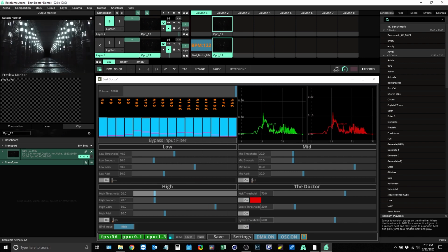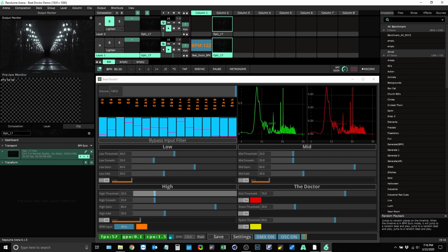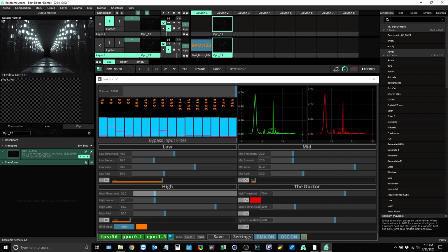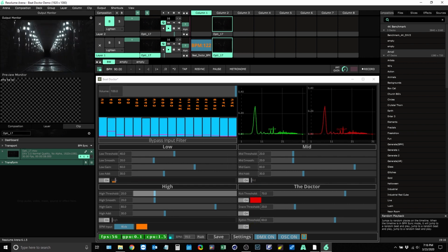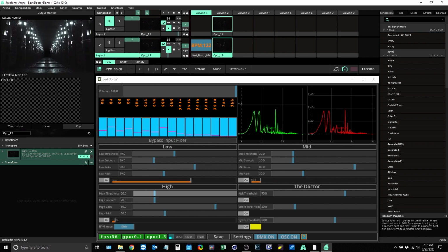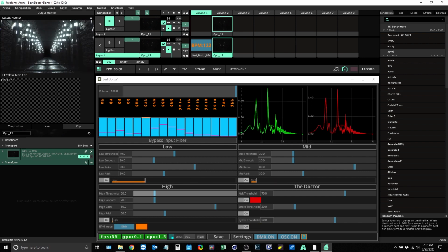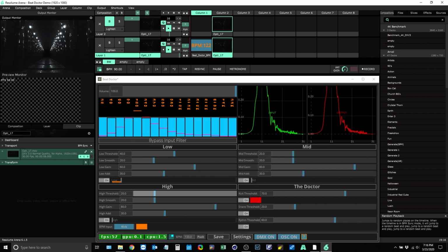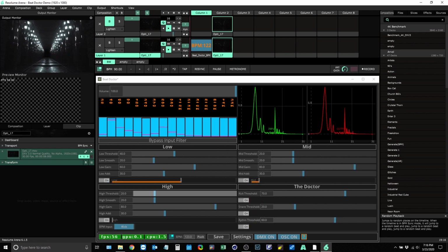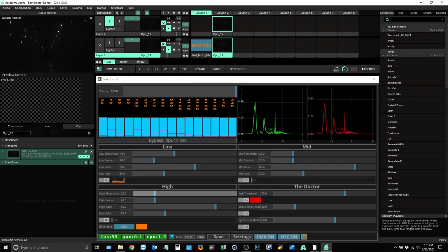So I like the Focusrite 2i2 for an example. So I'll get a stereo pair of balanced XLRs coming from our front of house audio engineer into that Focusrite box, and then in that box I will dial the gain up to where you see it clipping on the hardware, and then I dial that back probably 2 or 3 notches.